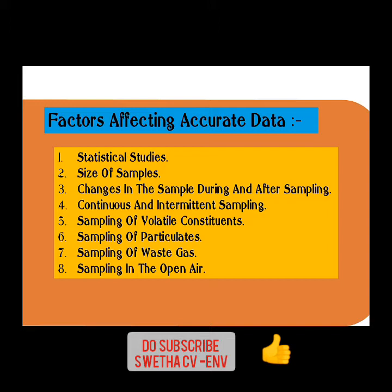So they say that the isokinetic condition is that the velocity of the particles and gases entering the probe nozzle should be equal to the velocity of the gas which is flowing out. So the input and output speed, or we say the velocity, should be equal. If that is the condition, then you will not make a mistake in terms of collecting these samples.